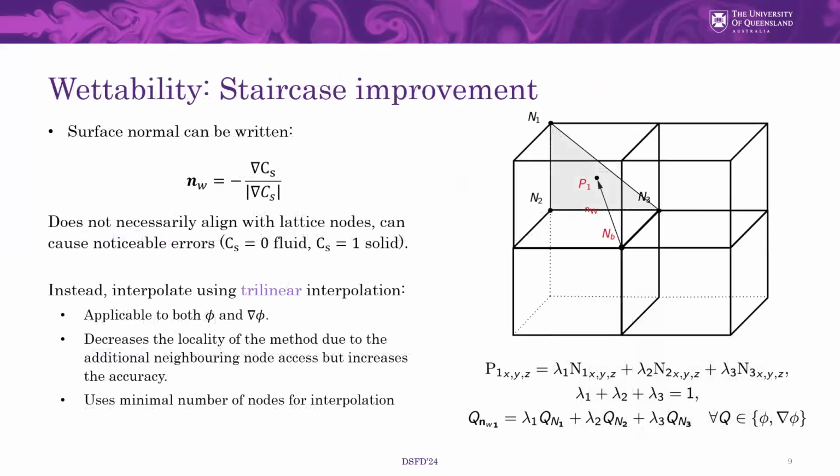So this is an idea of how we do this in the initialization stage. If we have a completely random field where we don't know the normal values, we can assign zeros and ones. We can do this gradient calculation and come up with some approximation of the normal. People generally do other things on top of this. They may smooth this. The nice thing about the fracture cases that we have is that because we're generating STL geometries, we actually have the normal directions as well, and we can prescribe those in the simulations. But in a more general case, this is the approach that we take.